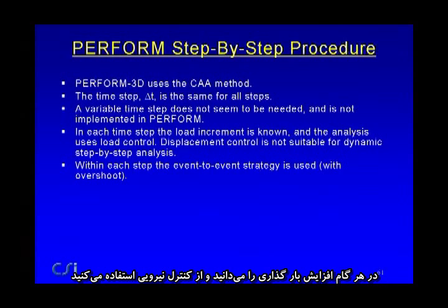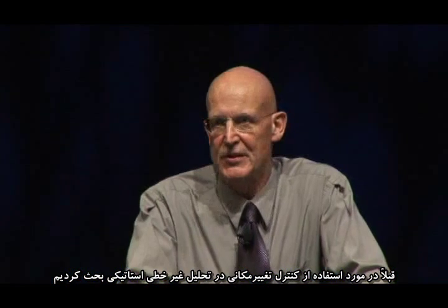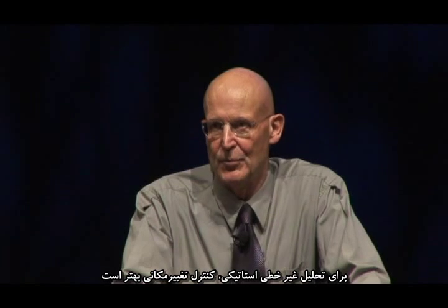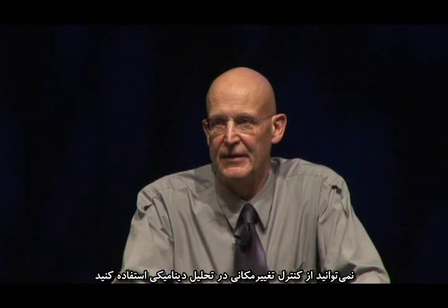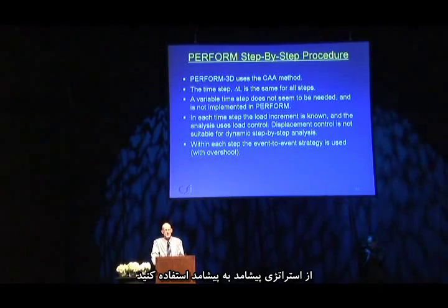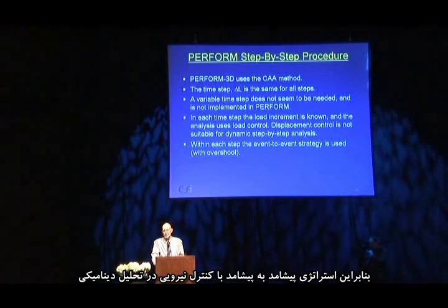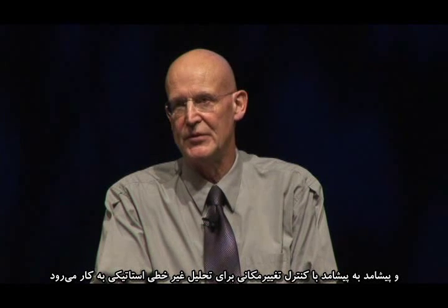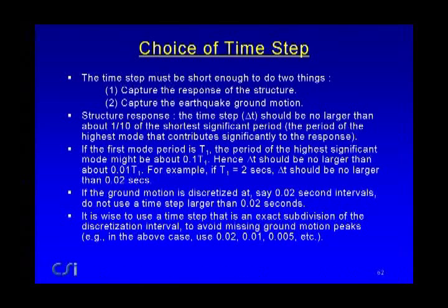In each step, you know the load increment, and it uses load control. We discussed previously using displacement control for pushover analysis. It's better for pushover analysis than load control. You can't use displacement control in dynamic analysis. You must use load control. And then within each step, it uses the event-to-event strategy. So it's event-to-event strategy with load control for dynamic analysis, and event-to-event strategy with displacement control for pushover.